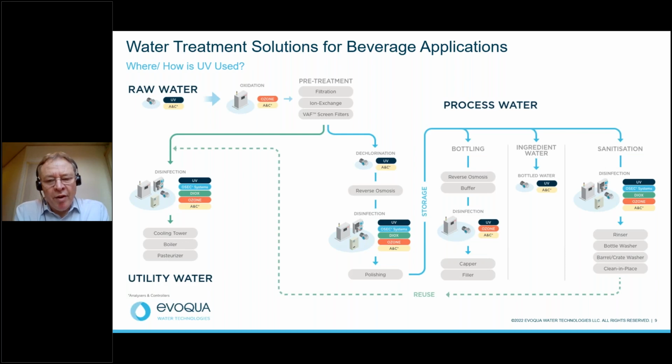And so once in the factory itself, where chemicals are used only periodically, the routine sanitization steps are not included in the ongoing disinfection process. So the absence of chemicals can eventually result in microbial growth. A few years ago, I was involved with a particular plant. Although they had a UV post-filter, they hadn't carried out any sanitization for a number of years. And then eventually the problem of microbial growth downstream in the factory became an issue, though it was many years before it became a problem. But again, regular clean in place systems are required if you're not going to use any residual disinfectant.